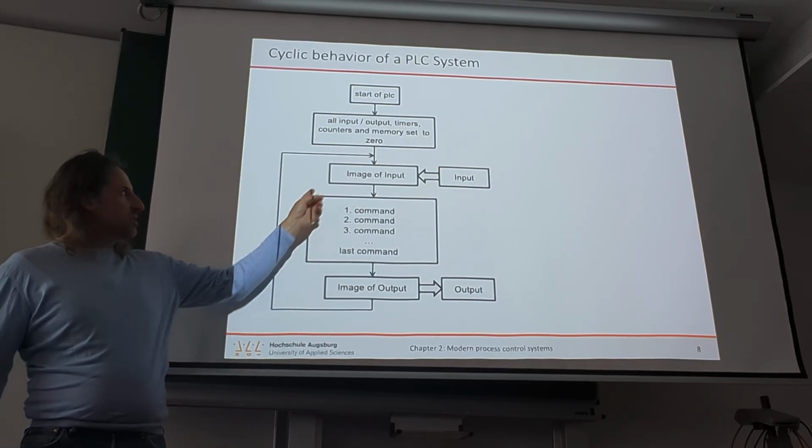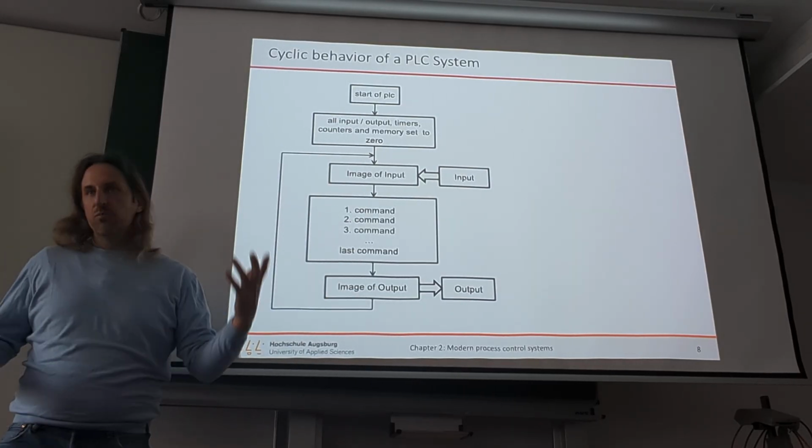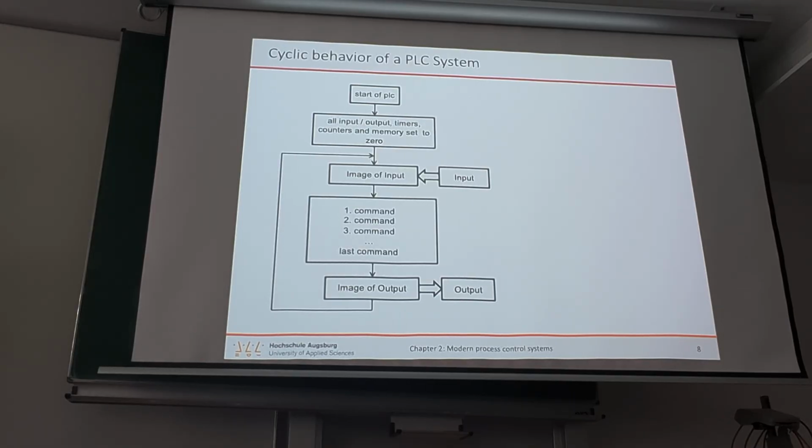outcome. But this is due to the fact that we have an operating system running on the PLCs, and they support this type of control execution. Automatically taking the snapshot of inputs, creating the outputs, and in between executing the code, and they then do the cycle again.